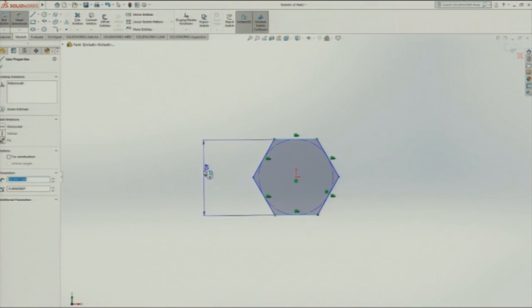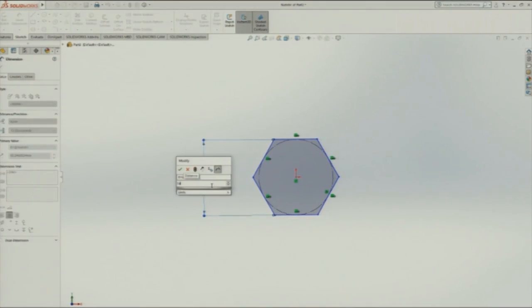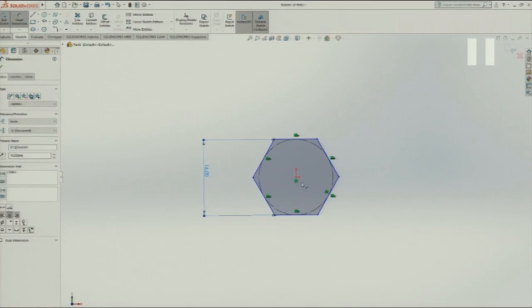So this is the width across the edges. Width across edges is actually 1.5 D plus 3 mm. So my D here is 8 mm. An 8 mm hole is there on the flange. I am going to put some value here, so that value 16 is selected. I am making a little change, selecting my own dimension. However, the width across corners has to be 2D. So this is a customized bolt that I am making here, not a standard bolt.